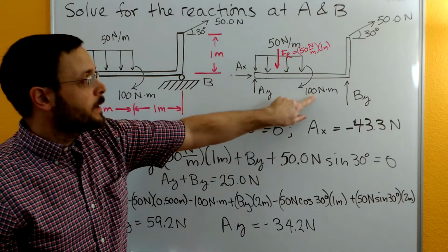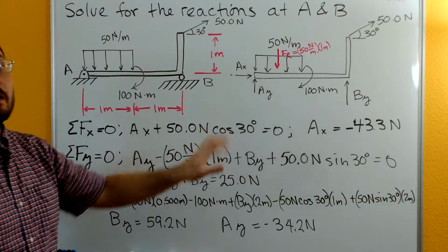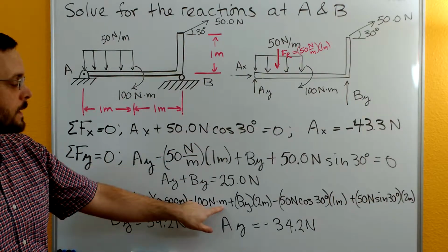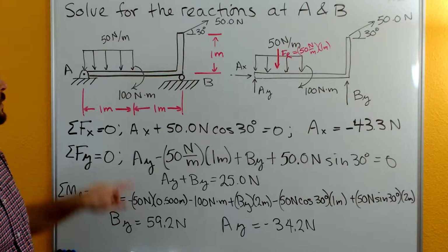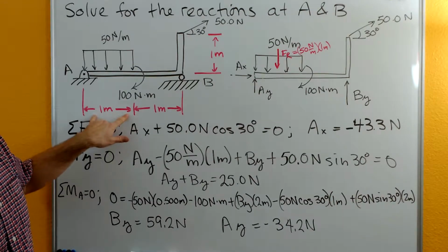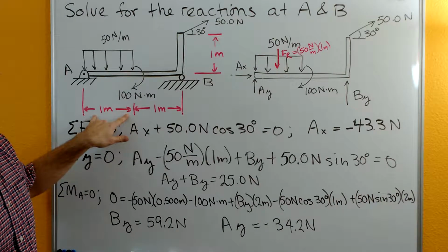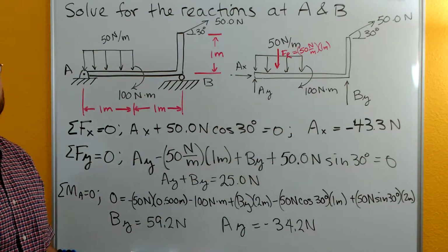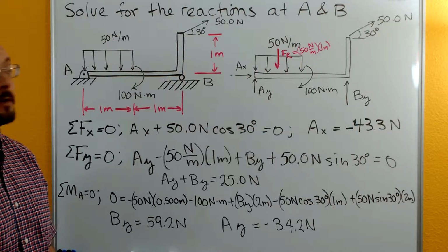Don't multiply that 100 Newton meter force by anything. It's already a moment. It's already in newtons times meters unit. So do not multiply it by a distance. It doesn't need it. That distance is already built in, just right in the couple itself.